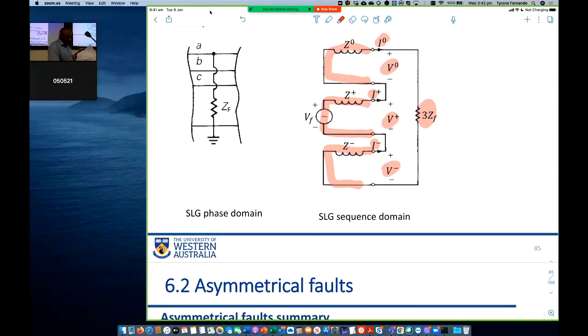So phase sequence, okay, equations, let's have a look. You have equation 14, right? Connecting the sequence voltages and phase voltages. No, the fault circuits are not given, right? So you would have to remember how to connect them.